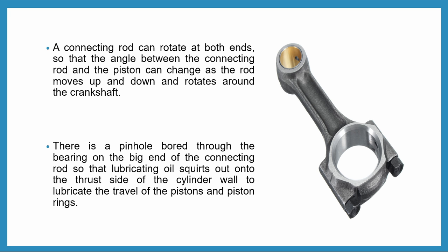Now coming to the pinhole bored through the bearing on the big end of the connecting rod. Here is a pinhole bored through this bearing on the big end of the connecting rod, for the purpose of the lubricant oil to squirt out onto the thrust side of the cylinder wall to lubricate the travel of the piston and the piston rings.